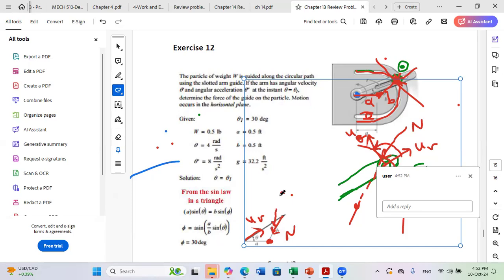We called it phi. David, yesterday you and I worked out the relation between theta and phi, and you can calculate phi. Okay, so now to project N, it's minus N cosine phi along UR and minus N sine phi along U theta, because UR is up like this and U theta is also up. So the normal, according to this assumption, has negative projections on UR and on U theta.